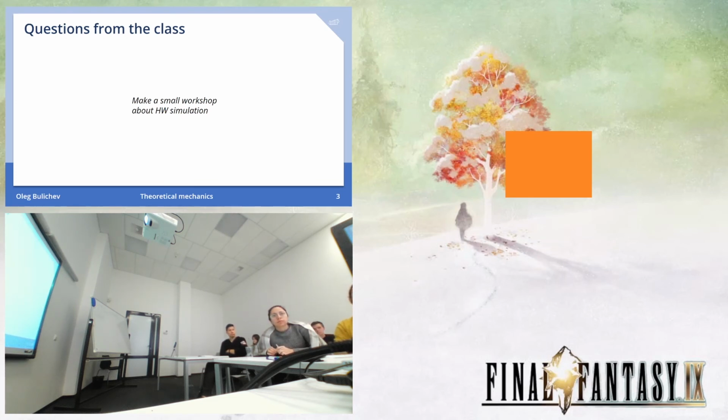So you solved it numerically. And how did you do it? I mean, after this, what did you do? I received numbers, so I used numerical differentiation to get the speeds. And how did you put it in the simulation? Just by having the speed coordinates. To form a vector, if you want to find the speed for A, the first point of the vector will be the position of A, and the second point will be the speed in X and Y coordinates plus the position of A.